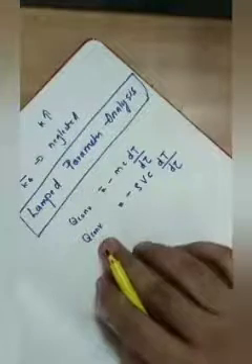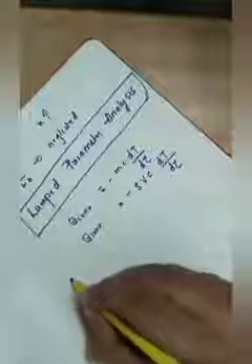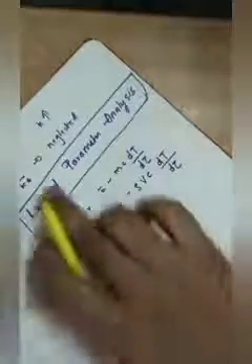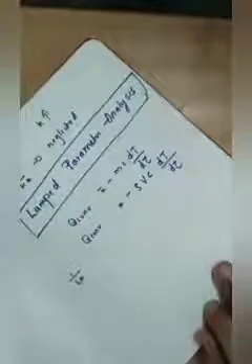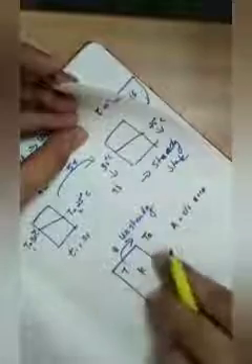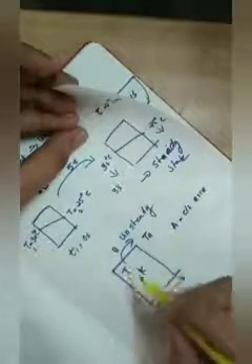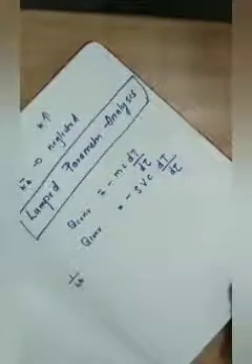Q convection means what? The convective resistance or surface resistance, 1 by hA. The 1 by hA value is not equal to 0, whereas the L by kA value is 0 in this analysis. And the temperature of the plate is T, because the temperature is constant throughout the x direction. So T is the temperature of the slab, Ta is the ambient air temperature, and Q convection is equal to minus rho V c dT by d tau.